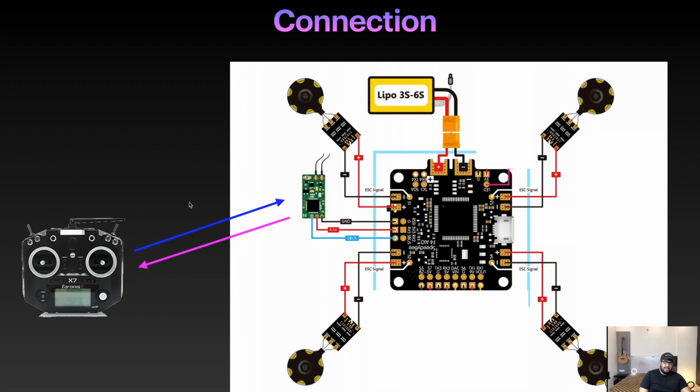It will send what value of roll I need, what value of pitch I need, what value of yaw I need, and what the throttle is, and these kinds of things it can send. All these values will be passed to the receiver, and the receiver will pass them to the flight controller. So the flight controller knows what the user wants. It knows that the drone operator wants me to, let's say, give a roll of 3 degrees to the right, or a yaw of 7 degrees to the left. These kinds of things the receiver will pass to the flight controller.